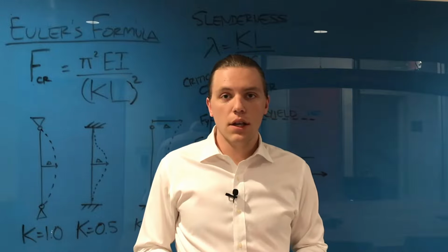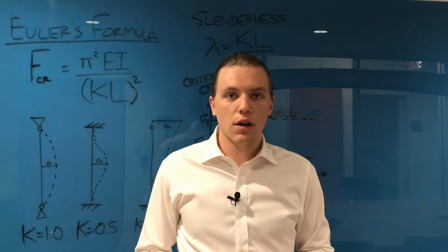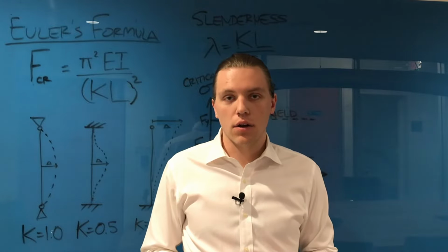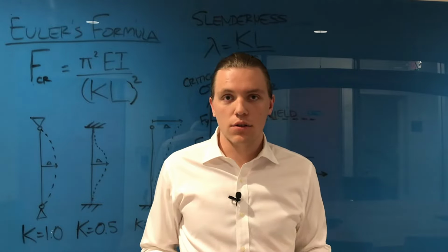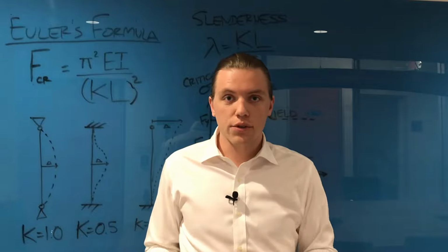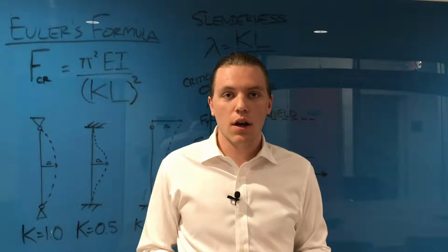It's actually common in structural analysis software to use a rational elastic buckling analysis via an eigenvalue analysis. And what this is basically going to do is evaluate the entire structure as a whole, groups of members and individual members for buckling.